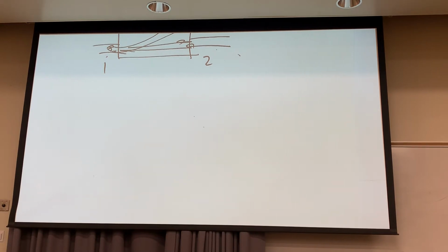Now, you know what triangulation is. If they have a bistatic case and they've got one distant receiver, another distant receiver, and you get some back here at the actual receiver, you're going to have 3 points. You could put a third one out there, and now you can triangulate and, basically just listening, find out the exact position of the object that caused a scatter. And that's why I'm telling you guys, because some of you probably get into radar.